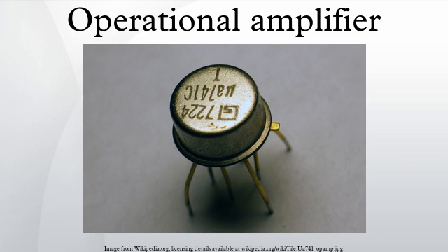DC imperfections. Real operational amplifiers suffer from several non-ideal effects. Finite gain. Open-loop gain is infinite in the ideal operational amplifier but finite in real operational amplifiers. Typical devices exhibit open-loop DC gain ranging from 100,000 to over 1 million. So long as the loop gain is very large, the circuit gain will be determined entirely by the amount of negative feedback. In cases where closed-loop gain must be very high, the feedback gain will be very low, and the low feedback gain causes low loop gain. In these cases, the operational amplifier will cease to behave ideally.